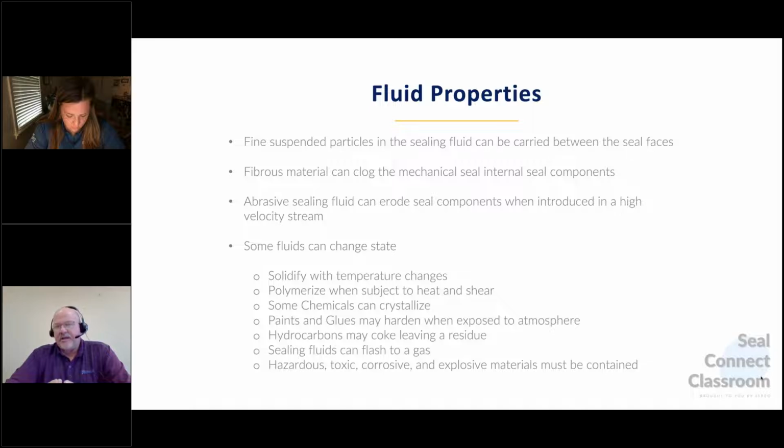And if you're flushing or using one of the discharge bypasses or things like that to create the environment for the seal to run in, some of those products that you're pumping, like sand and things like that, can be abrasive, and running that back into the seal chamber at higher pressures can be abrasive to the metal parts.